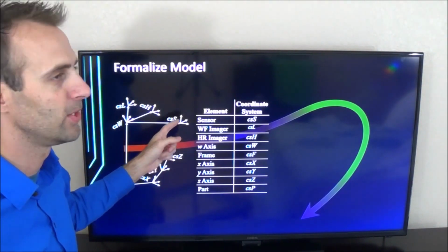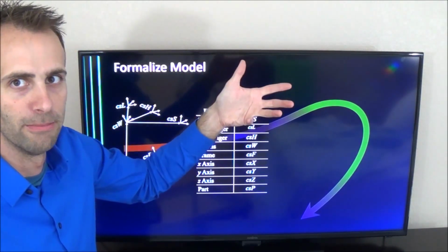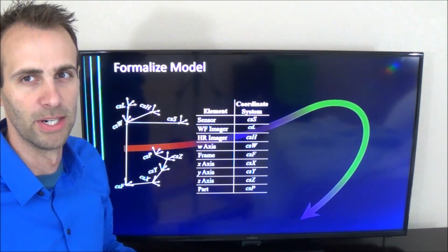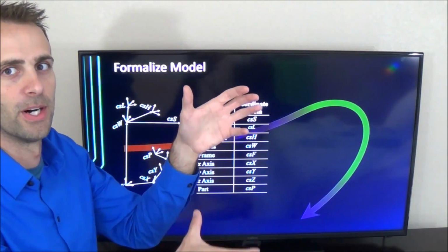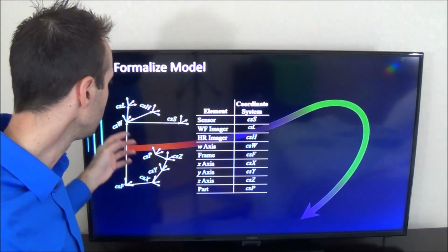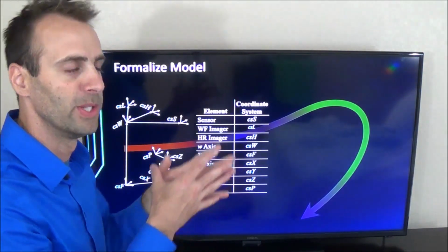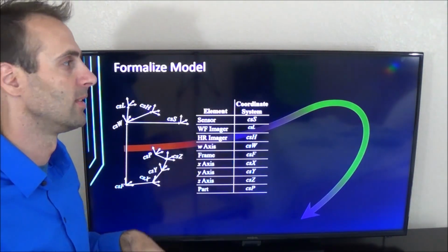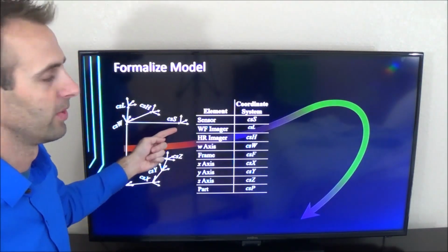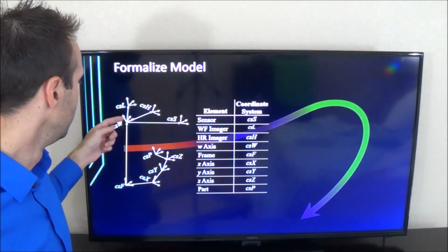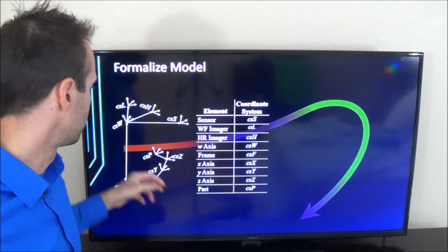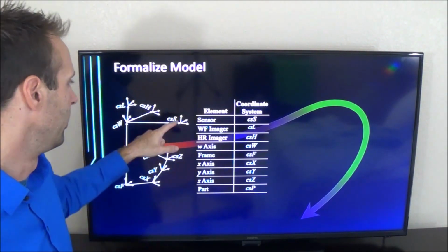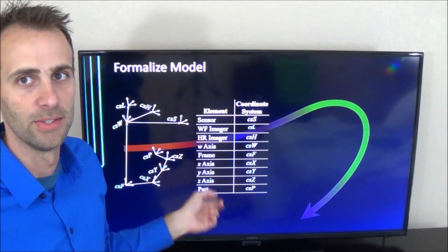It doesn't mean that if I change the milling cutter in a milling machine that I have to switch to a different coordinate system. That coordinate system just is going to have a different offset with a different tool offset. So these branches really represent, within the same program, literally physically different machine elements. And you could do that branch with your tools, like we said with the 3D printer, and you could also do it with the part. So there could be a branch here and a branch here, and then your software can just pick the one chain and the math that gets you to what you need.